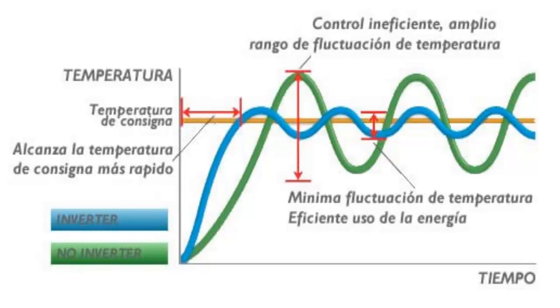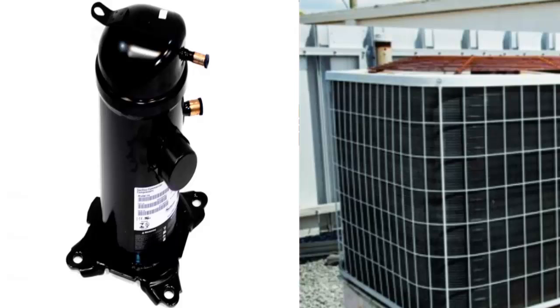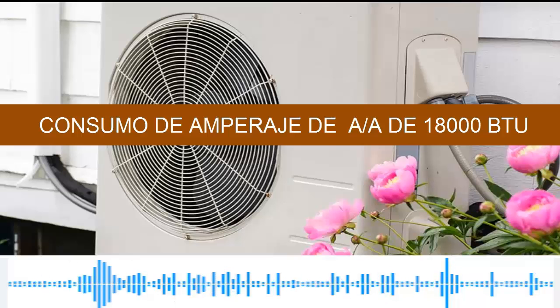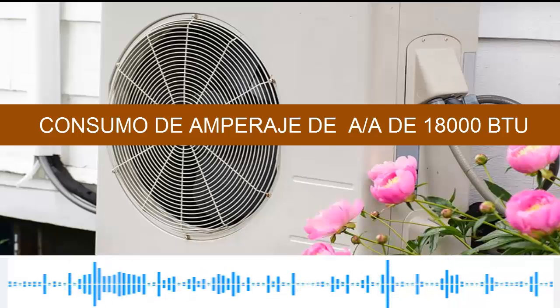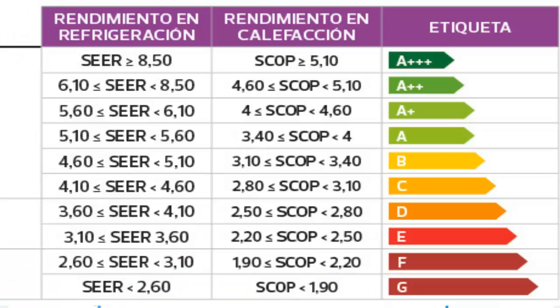We will calculate this average current value, knowing the SEER, Seasonal Energy Efficiency Ratio, value. SEER is measured under various working conditions, with the same room temperature, but changing the outdoor ambient temperature from 18 degrees Celsius, 65 degrees Fahrenheit, to 40 degrees Celsius, 104 degrees Fahrenheit. The equipment's power in BTU per hour is divided by the SEER value to obtain the average power consumption in watts.